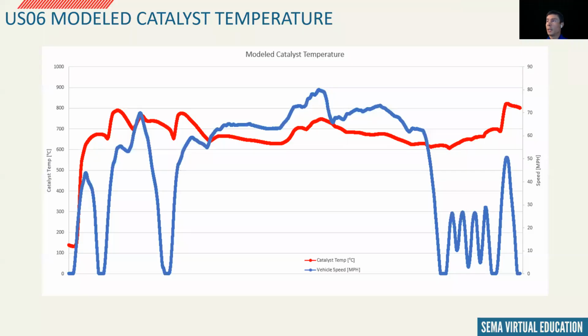We have talked a lot about catalyst temps a fair bit. Catalyst temp targets for activating the catalyst after a cold start, catalyst overtemp to control catalyst temperatures. When we talk about catalyst temperatures, we are talking about mid-bed catalyst temps. The catalyst mid-bed starts about an inch back from the face of the catalyst substrate.